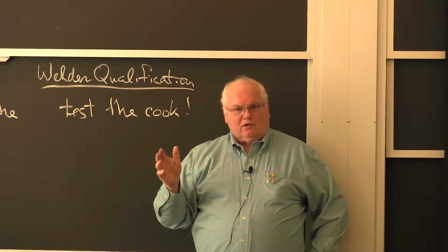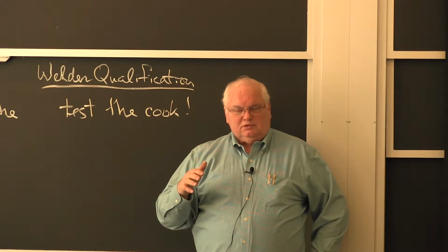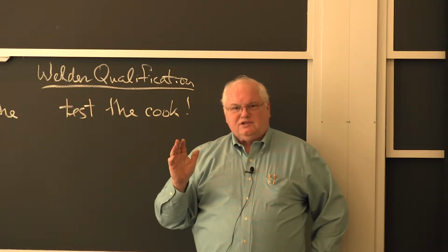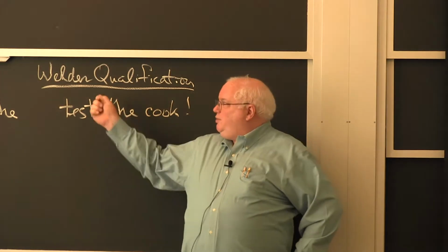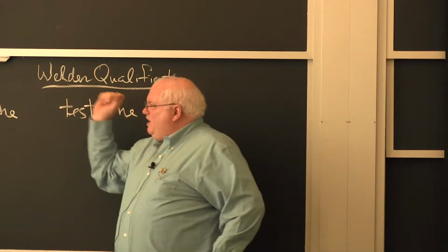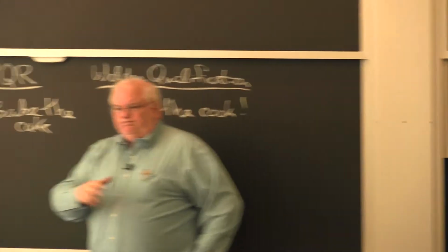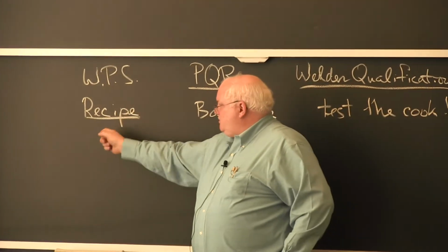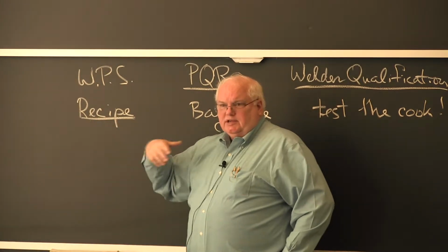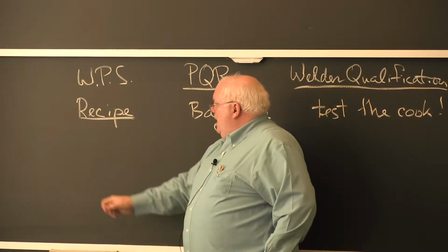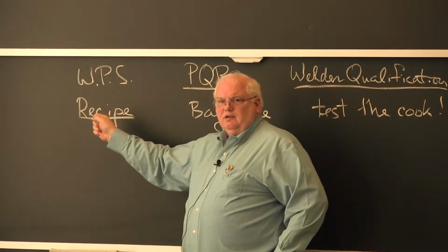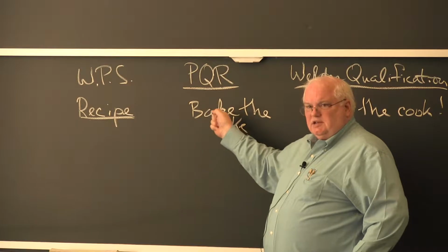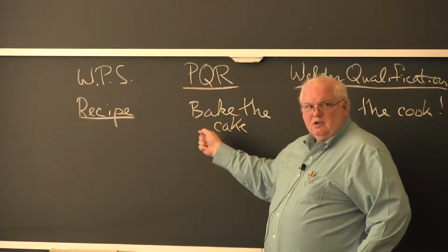It's a qualified welder under the code. However, in the last 10 to 15 years, there is such a thing as a certified welder. It used to be that every company, if you were building a bridge, you'd have to have your company specification for taking A36 steel, which is garden variety steel plate, and you'd have to have your recipe that your company has, and then you'd have to test it, and this testing might cost $2,000 or $3,000.